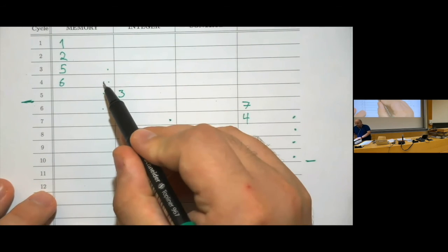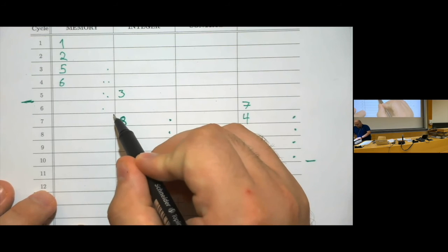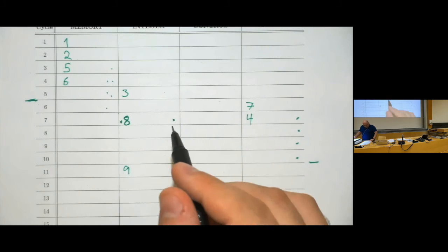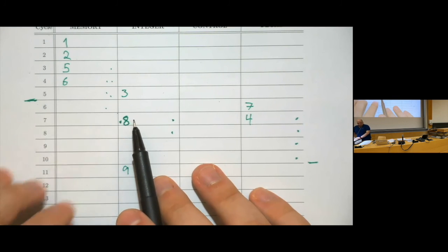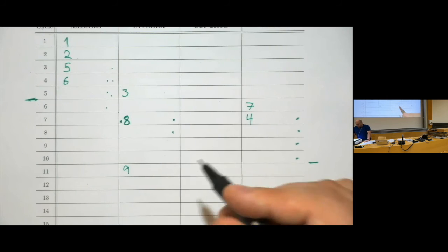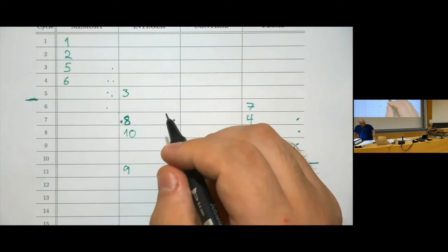So the latest one of them is going to take 3 cycles. So that's going to become available for use here at this stage, right? However, note that the instruction that we want to schedule is an integer add, and we've already scheduled an integer add for this point. So what we can do is schedule this 10th instruction right after it, right? Okay.